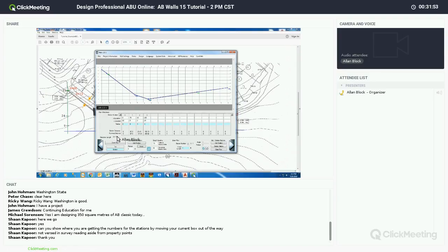And it also allows you to modify your plan view, because as an industry, we don't really like to see mitered corners. Now the contractor has to cut all of those blocks, and you're going to have a seam right at that corner, and as these walls are meant to flex, that seam might open and close depending on the movement, so it might also create an eyesore. So what we would prefer to see are curves or a radius or radii.